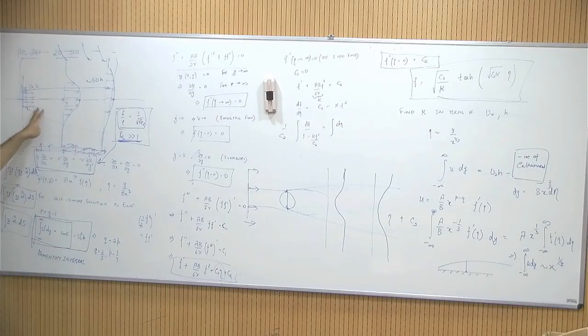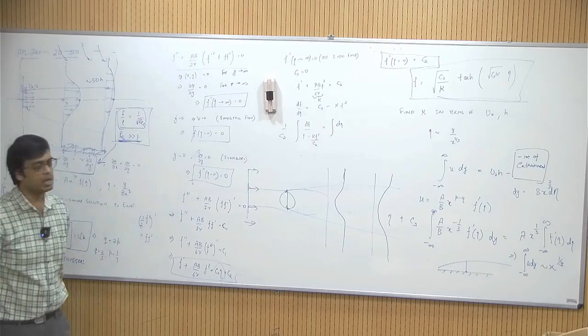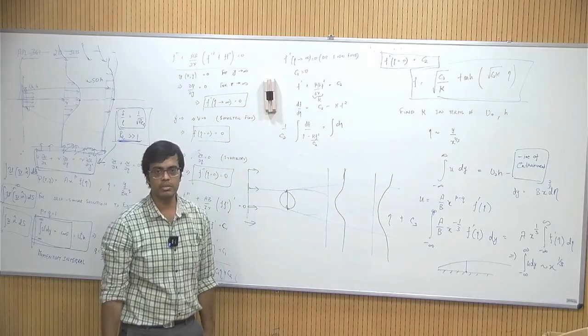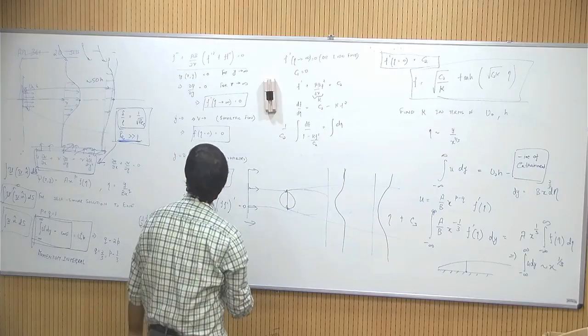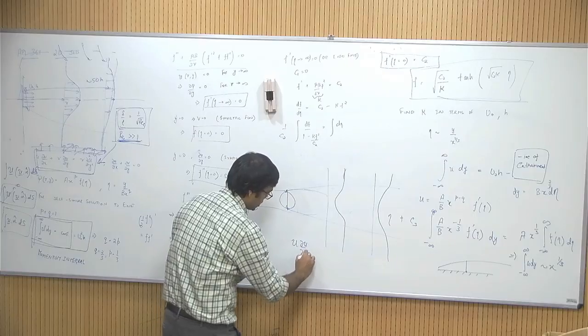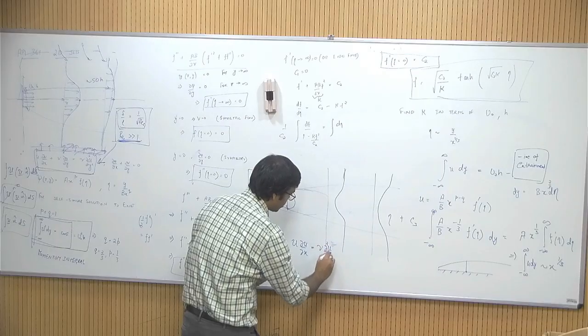Here what happens is you say you move far away from the jet. Now your intuition would say, okay, move far away from the body. Why don't you get a self similar solution? You will get a self similar solution, but that will be simply a diffusing solution.